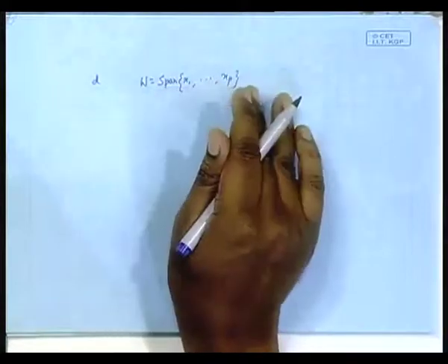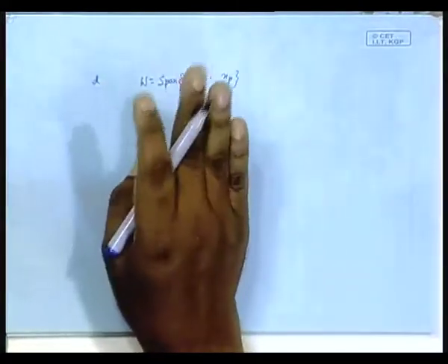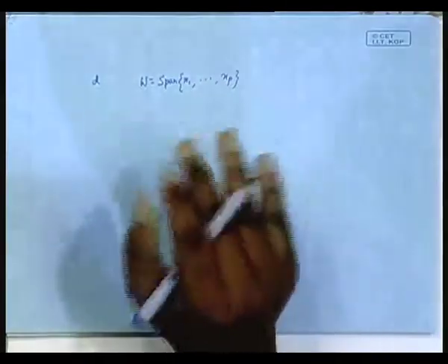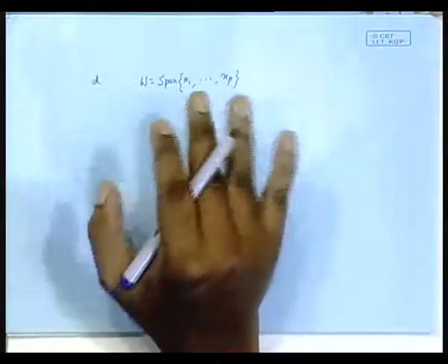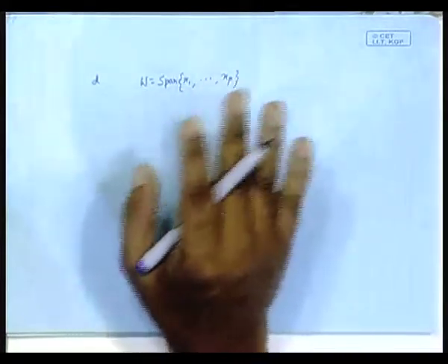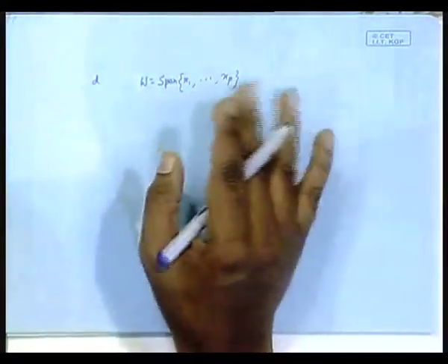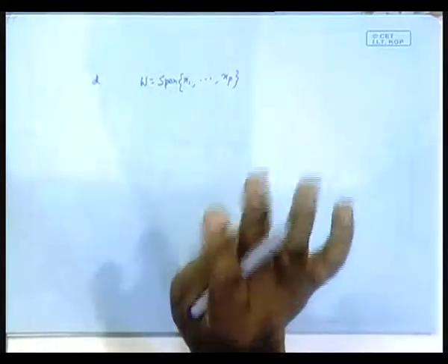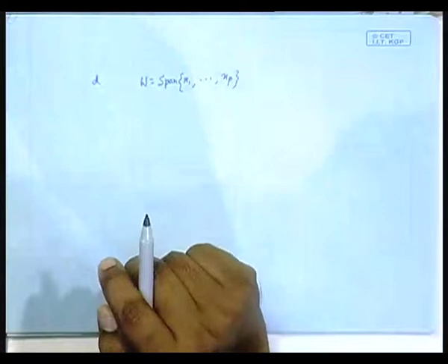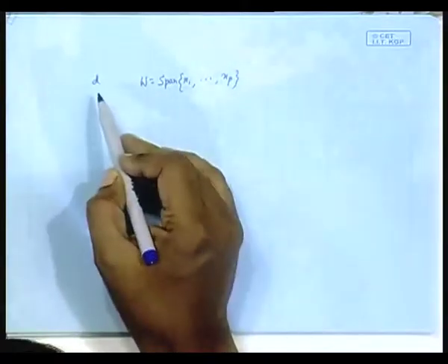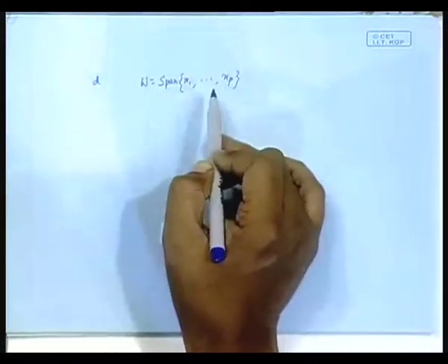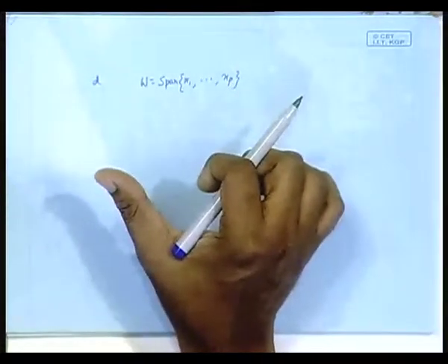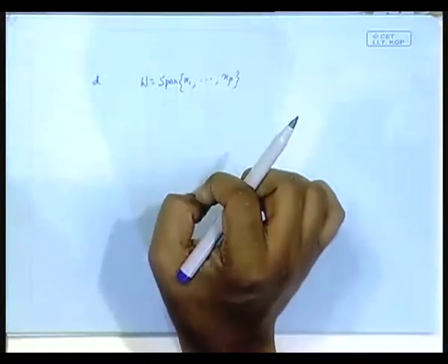We have the inner product there, and the inner product is a correlation. For this RLS business, for the time being assume everything to be real, because complex will be a little more difficult. Whatever result we get for real, we can easily extend to the complex case, but for now assume we are dealing with real valued random variables. We are given the inner product in the space as the correlation between any two random variables: E of xy is the inner product between x and y.